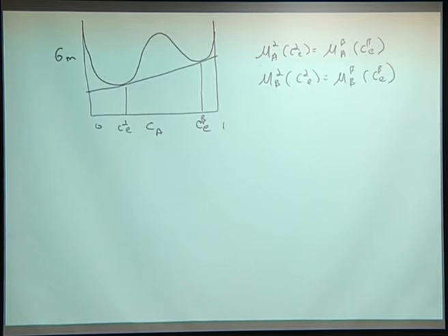I drew this free energy curve tilted for a good reason. If you have a material that has a certain alloy composition, let's say here, that has an alloy composition there. That's a little bit too high for me to point. Let me do this. What this says is that if you started with a material at this composition, it will phase separate into two phases of different composition.